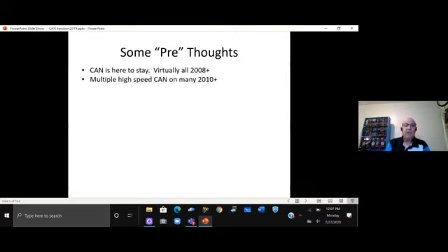CAN's here to stay. Multiple high-speed CANs became popular all the way back in 2010. Okay. So now you look at a wiring diagram for a 2014 or 15 or 16 or anything, and you realize that you've got 3 high-speed CANs, 1 low-speed CAN, and maybe even a communication bus where all communications occur.